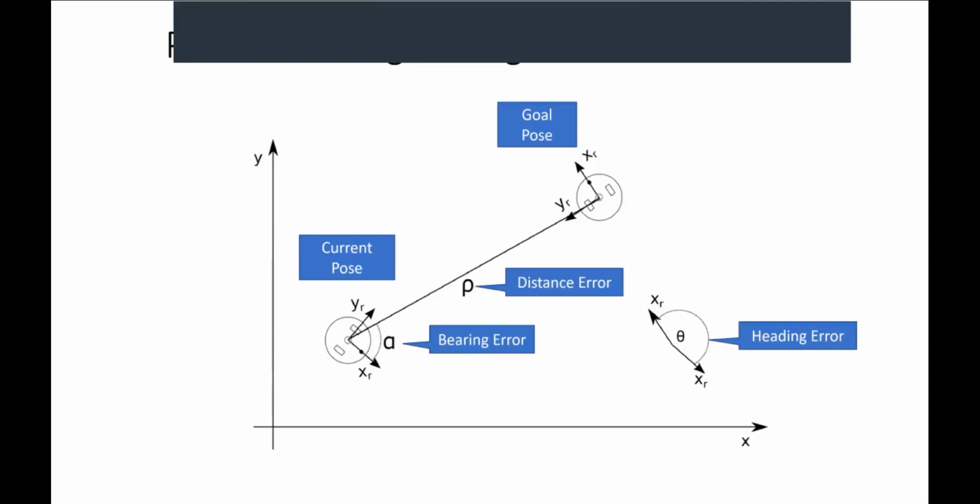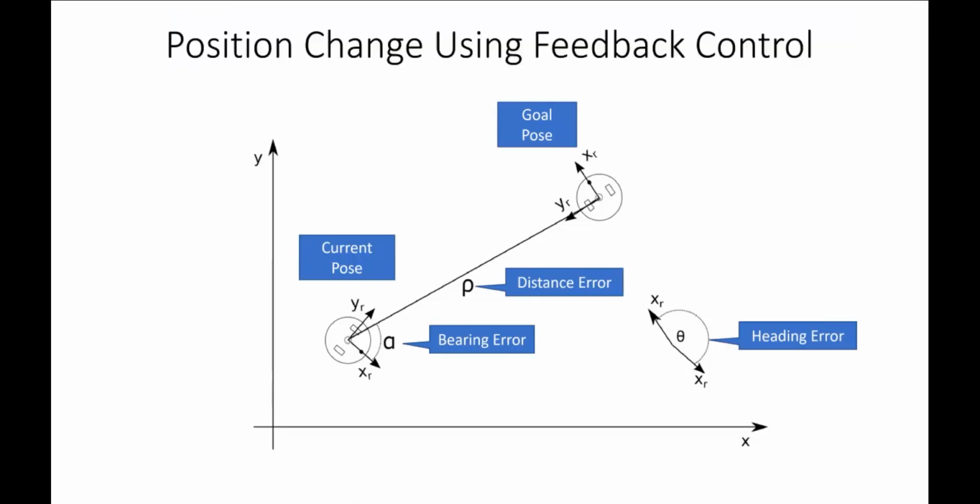So in your lab tomorrow, you're going to be explicitly computing these 3 sources of error. So you will be given a current pose of the robot. You're going to maintain that current pose through odometry. And then you're going to pick a waypoint, or a location and a pose that you want your robot to be in, say maybe relative to where you're currently at. And then you're going to use these sources of error along with the inverse kinematics equations to get your robot to that point.